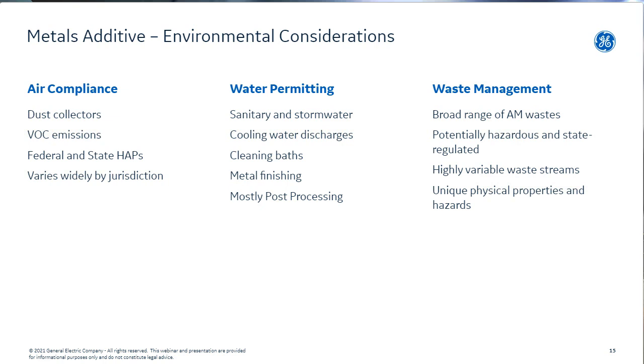Also, when you're operating, as an example, with binder jet technology, you need to cure the material. There can be some volatile organic compound creation around that, which maybe triggers thresholds for exhaust systems. There are specific federal or regional regulations around how to do that. In this situation, I recommend you consult a local specialist or your regulator to help you with that.